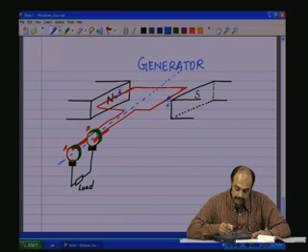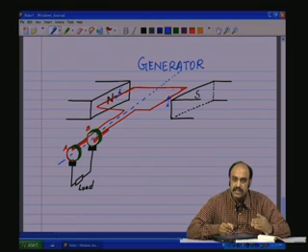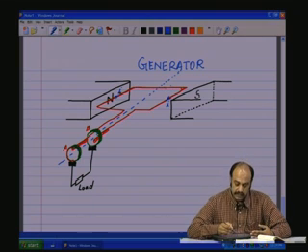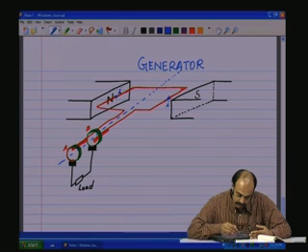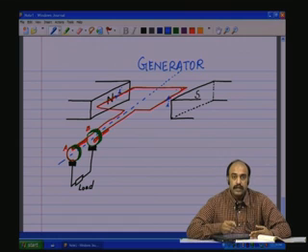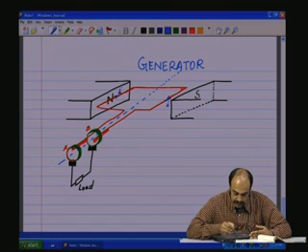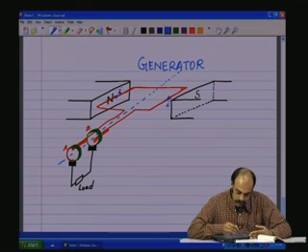Now, this is in a perpendicular direction, this is along the field. This portion of the conductor does not cut the field, does not see any differential flux amplitudes throughout its rotation, and therefore there is not going to be any induced EMF on this line and this line. So, these two are going to have currents induced, one in this direction, one in that direction, and this is fortunate for us because we have drawn the coil such that current can flow like that through this coil, flows through this coil and comes out through this.